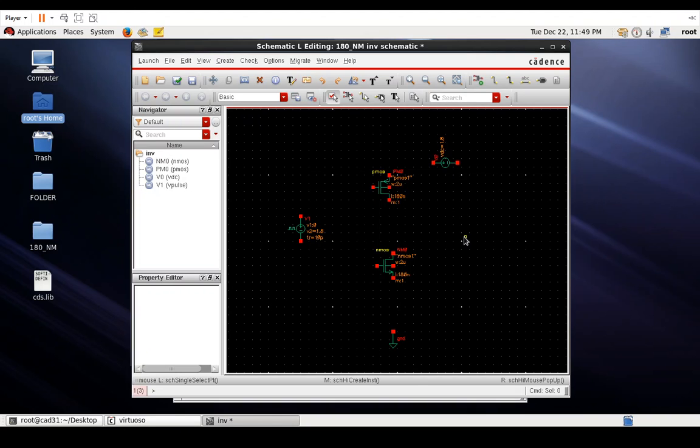And the wire is not a component that you insert, but it is just something that you can draw by clicking W on the keyboard. So see how the cursor will change when I click on W. Okay, so now wherever I want the connections, the from point, click once, remove your hand from the mouse and move it to the to point and click again, and you will get a wire. If you want it to turn at a particular point, bring it there, click there and take it. Okay, and continue with all the other connections.